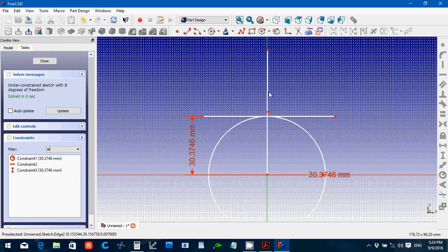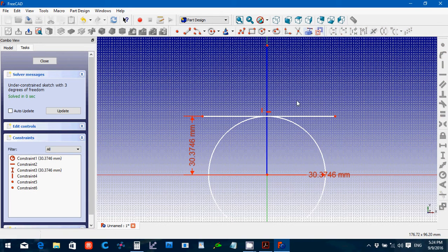Now for some reason this didn't connect up here, I guess, because you can see it's at an angle. So I'm going to go ahead and give that a constraint so it's straight up. And it didn't connect there either for some reason, even though I know I selected it. Give it that type of constraint. So now I shouldn't be able to move it. Good. Now both of these are construction lines, I believe. So we'll turn those blue by going like that.